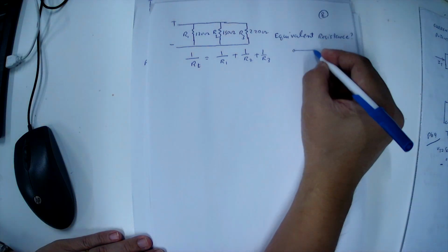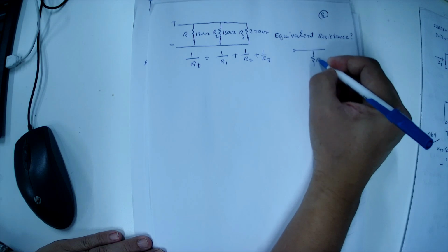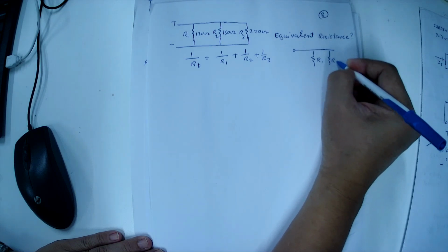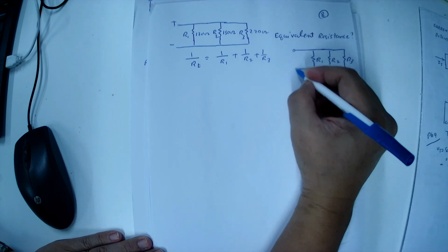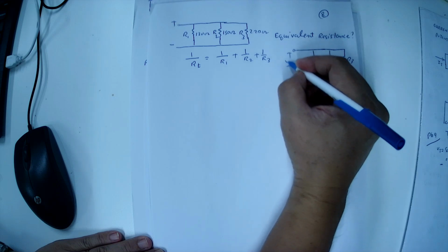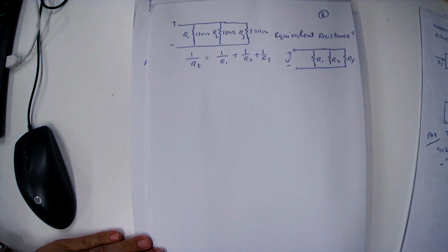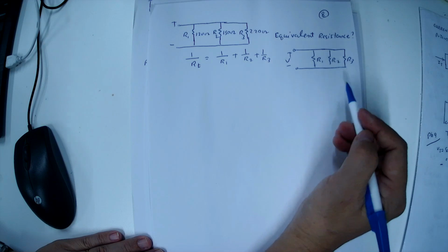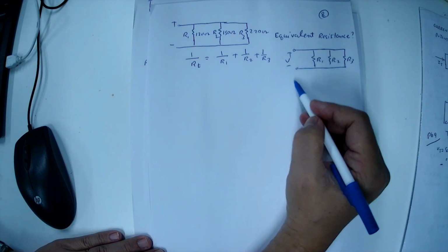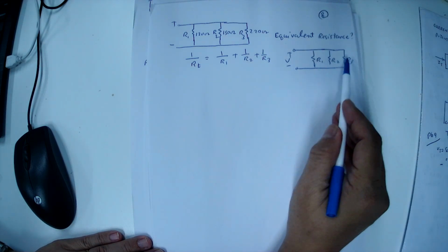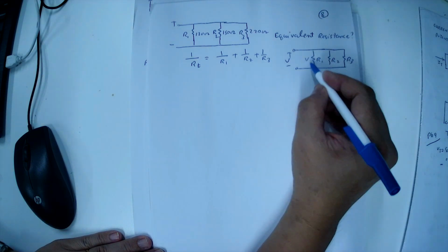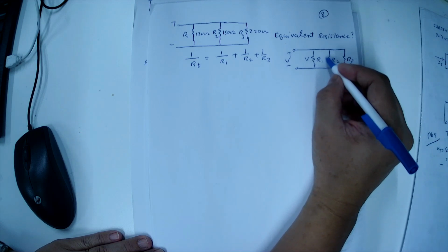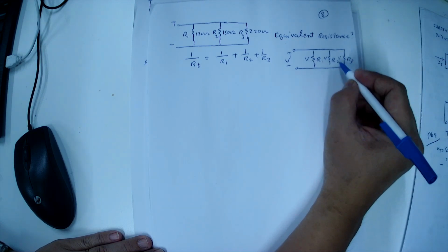And if you connect the resistors R1, R2, R3 in parallel, then connected to the voltage source V, in this case all the resistors get the same voltage. Supply voltage V, resistors R1, R2, R3 are connected in parallel. Therefore, the voltage across R1 is V, voltage across R2 is V, voltage across R3 is also V, the same voltage.